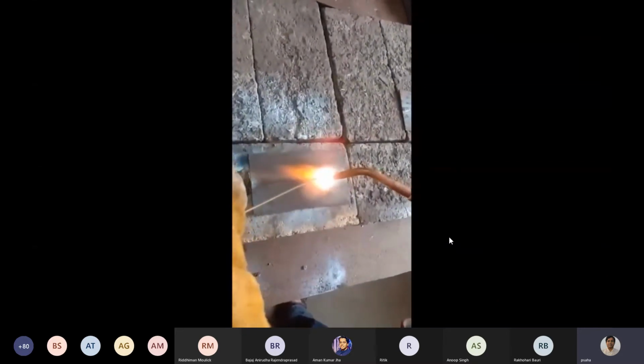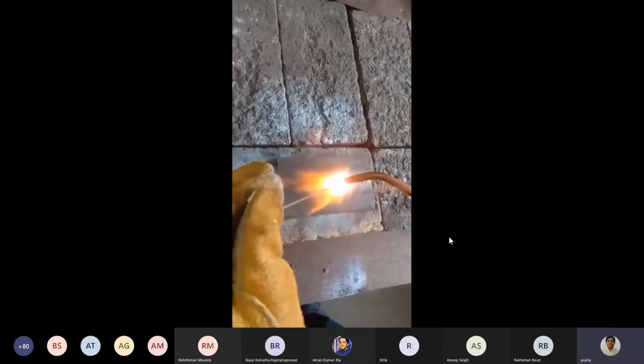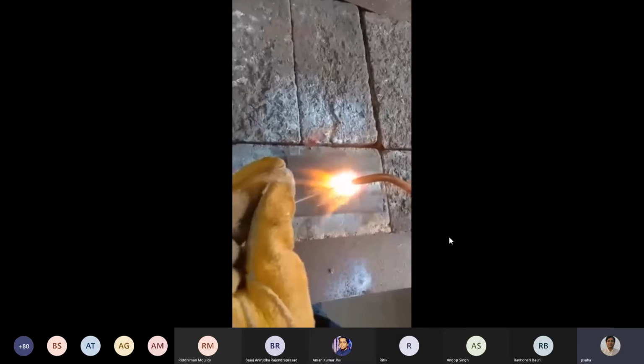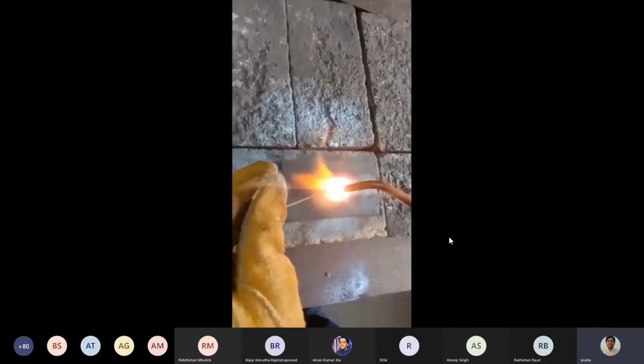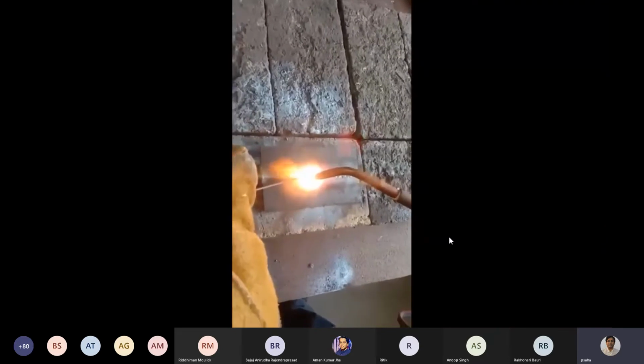And accordingly you have to add the filler rod and move the filler rod forward and backward, and also gradually move the flame towards the left hand side. Here we are using the left hand technique or leftward technique because it starts from the right hand end towards the left. The flame angle to the workpiece is about 60 to 70 degrees, and the filler rod angle you have to maintain is 30 to 40 degrees with the workpiece.